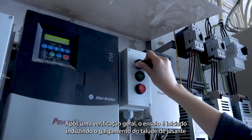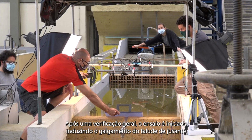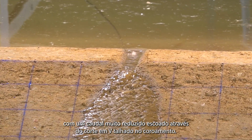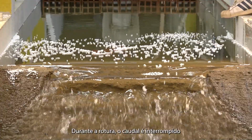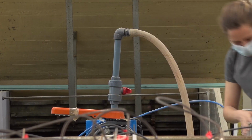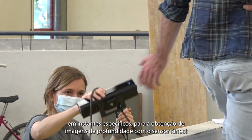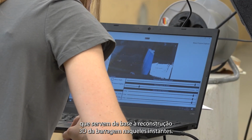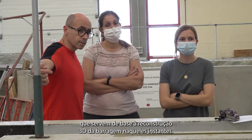After everything is checked, the test is initiated by inducing the embankment overtopping through the V-notch carved in the crest with a very small flow. During the failure, the flow is interrupted at specific instants to acquire depth images with the Kinect sensors. They are used for the 3D reconstruction of the eroding dam at those instants.